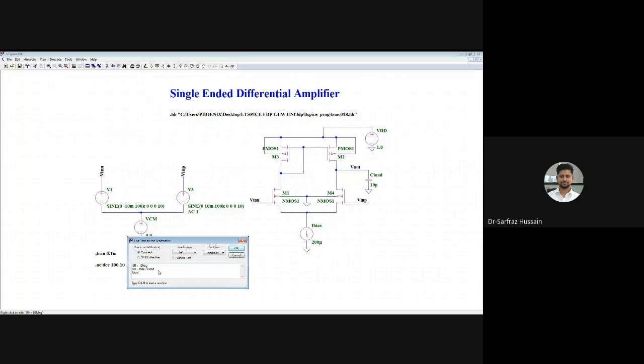So I bias is equal to slew rate. If we take 10 mega, then we have to multiply it with the load capacitor, 10 pico. Let us see what value we get. So 10 mega times 10 pico is minus 6, that is micro.